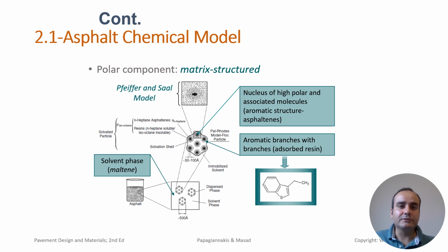Asphalt is composed of various fractions of hydrocarbons that can be broadly divided into the following categories. Asphaltenes are high molecular weight solid-like materials that provide structure and stiffness to asphalt. Maltenes: this fraction includes resins, aromatic hydrocarbons, and saturates.